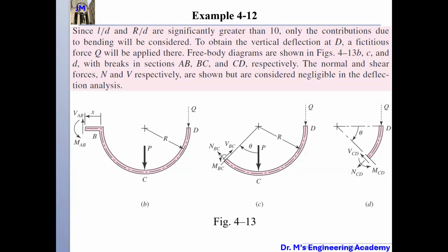If I change the geometry of this one or change the load, you should be able to give me an answer, right, if you know what we have done here. But this here is important. Based on my previous teaching experience, some students ask me, why do you just use the bending moment? What about the contribution of other terms? So this is the reason: because it is a very thin, very slender beam.